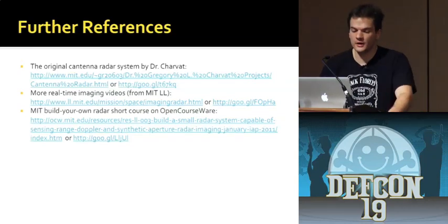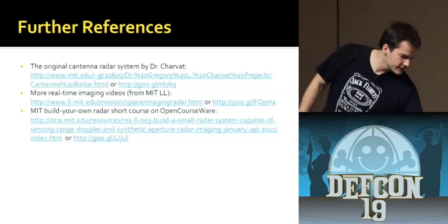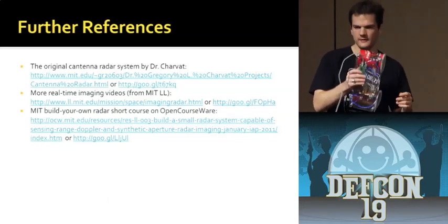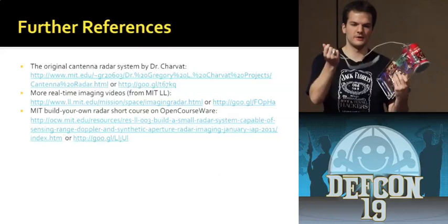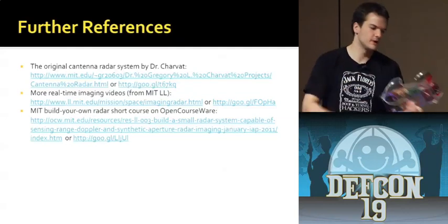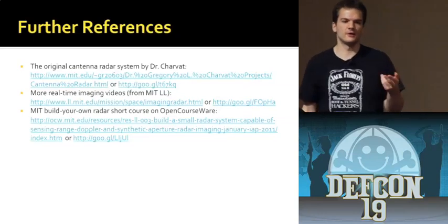Oh, yeah, actually that's worth talking about. He asked what the power requirements were. I believe this entire system uses about 200 milliamps at 5 volts. So like I said, it's easily powered by the USB port. That's the only power source here. The original was powered off of 2 sets of AA batteries. So that's about all you're talking about.